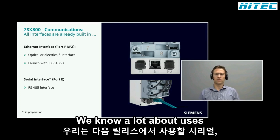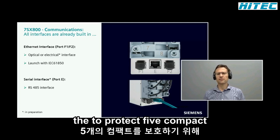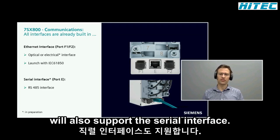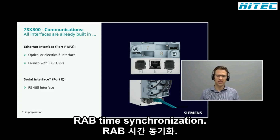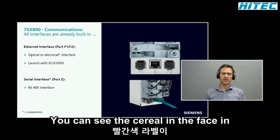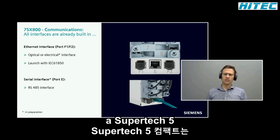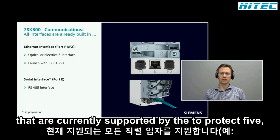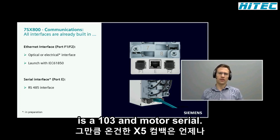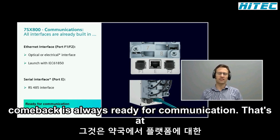We know that a lot of our users still like to use serial protocols. Therefore, in the next release, the SIPROTEC 5 Compact will also support a serial interface that can alternatively be used also for IRIG-B time synchronization. You can see the serial interface in the center of the rear, labeled as port E. The SIPROTEC 5 Compact will support all serial protocols that are currently supported by the SIPROTEC 5, for instance, IEC 103 and Modbus serial. So you can see the SIPROTEC 5 Compact is always ready for communication.